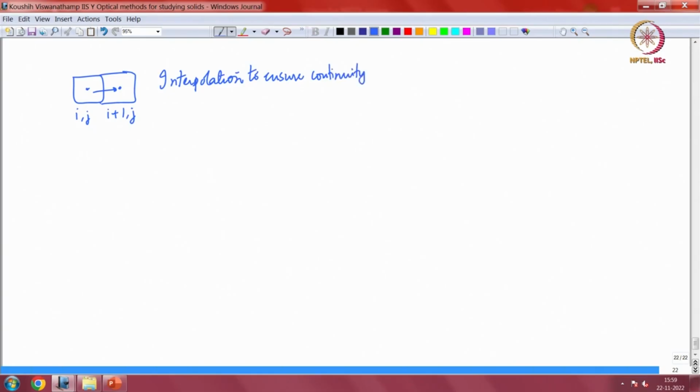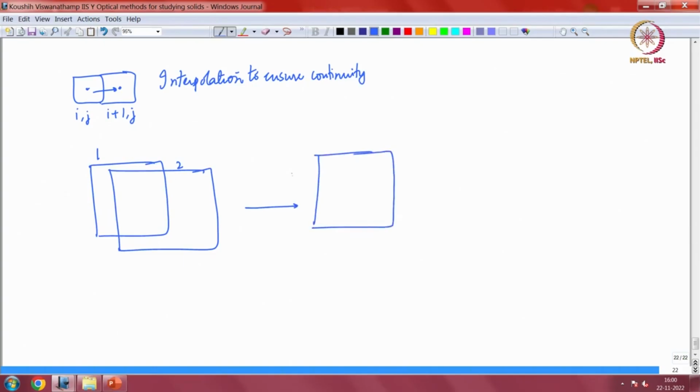And typically what you will have to do is, remember we said that there are 2 images that you do this for. I showed you image pair 1 and 2, and if you have a sequence you get a strain field at every point, some value of the strain tensor basically. So, now you will get the vector u v and the strain tensor u x, u y plus v x and so on at every point, but remember this is the incremental strain.